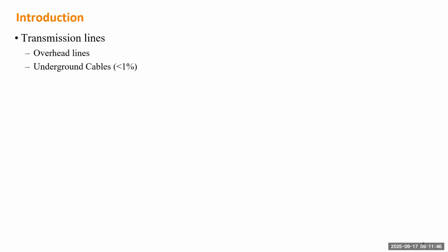not underground cable. But in some areas, like a rich area, the people don't want to see the overhead lines, so they prefer to pay more to put the lines underground. So that can happen. At the end of this section, we'll explain the difference between overhead lines and underground cables. Even though they can be modeled by the same set of parameters, in general, underground cables will have more capacitance than overhead lines.